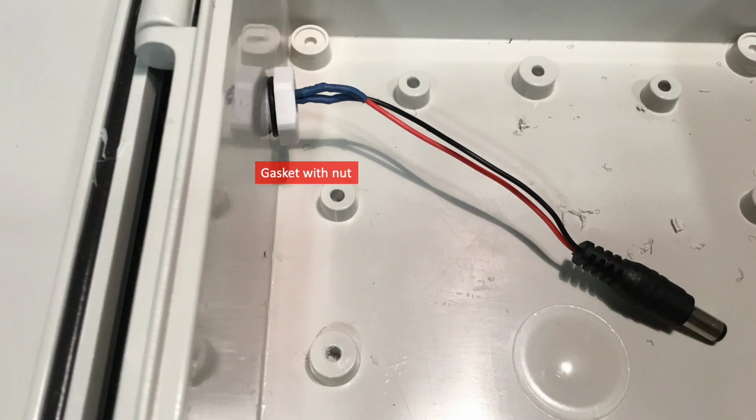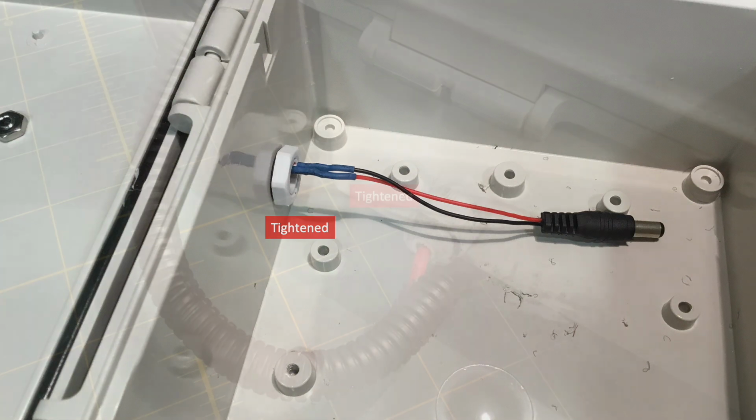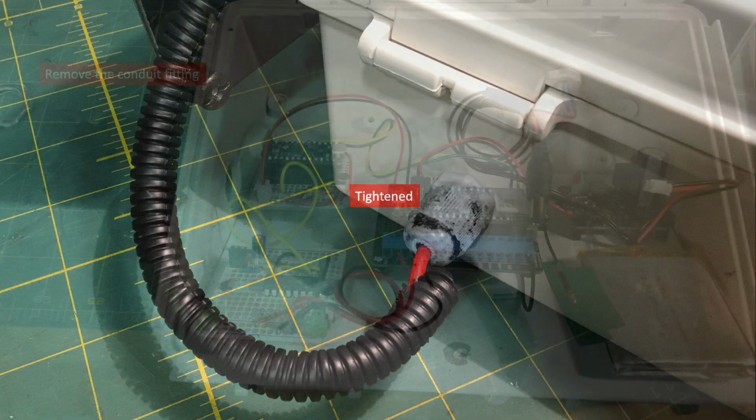Thread the barrel plug into the box, insert the watertight fitting, and attach the gasket with the nut on the male part of the watertight fitting on the inside of the box. The nut should slide easily over the barrel plug for this step. And then go ahead and tighten the nut. And on the other side of the box, tighten the watertight fitting, which should in turn take hold of the cable, making it more difficult to pull out.